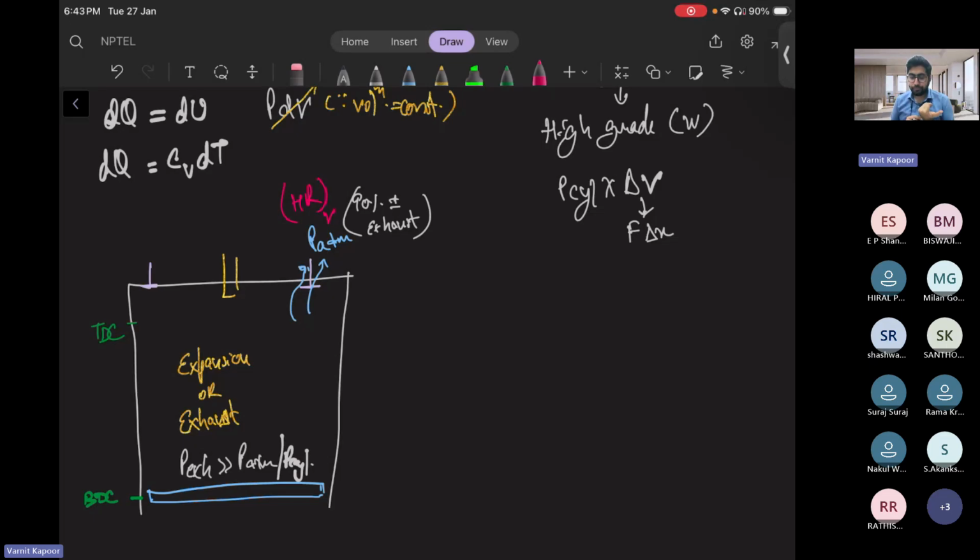I was saying that heat rejection is at constant volume because at this instant, when the piston is at the bottom dead center, 90% of the gases have come out, because at that instant the exhaust valve will open. Because of that, 90% of your gases carry forward outside at atmospheric pressure, and that means your gases are carrying some heat because the fuel has been burnt, and that low grade form of heat has been carried outside with the exhaust gases.